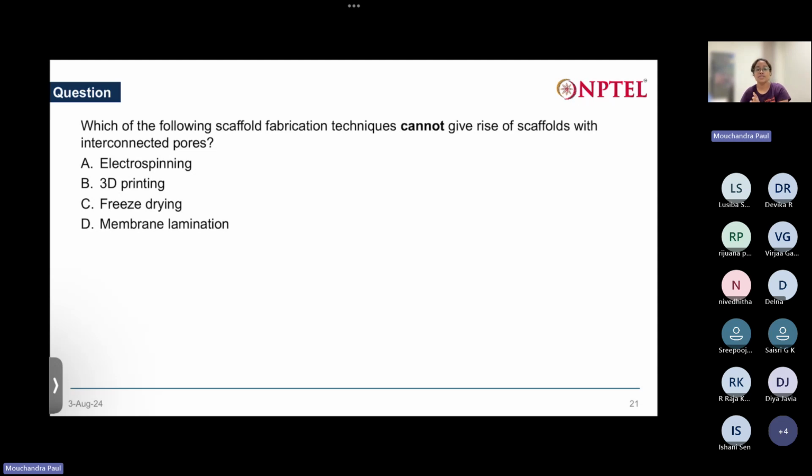Just opposite to it, there is a surface. It can be a drum or a plate, and it is of opposite charge. So what happens? Due to charge interaction, the viscous polymer turns its morphology from a drop to a cone-type shape, and very thin fibers start coming out and deposit on the oppositely charged surface just opposite to it.